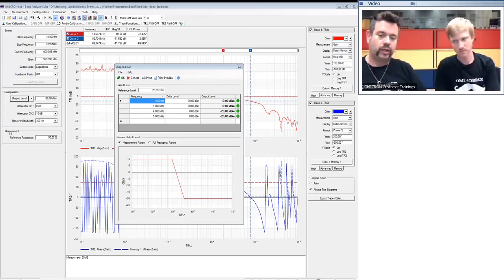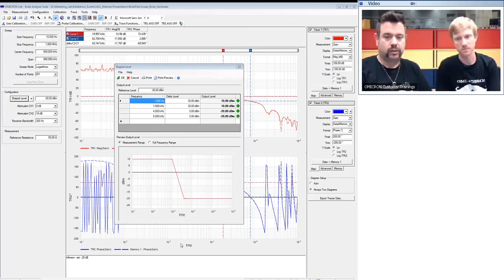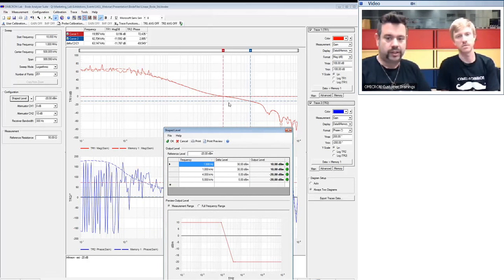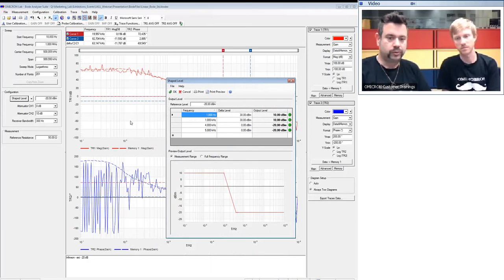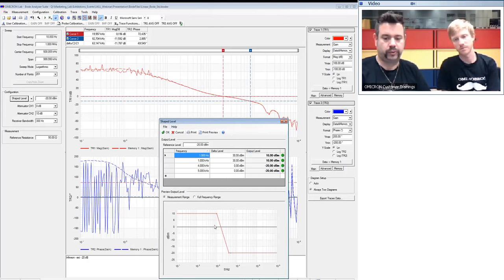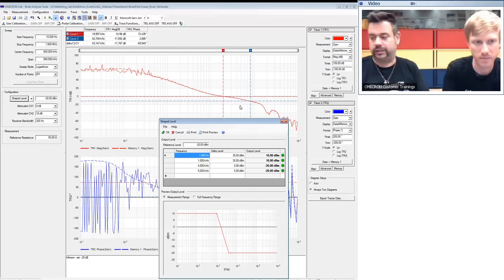Usually you have to have a small distance, so our pass-through point is somewhere in the area of 20 kilohertz, and the noise stops, as you can see here, around 100, 200, 300, 400, 500 hertz, so it's definitely enough if we just increase the signal up to 1 kilohertz and then slightly reduce it until 4 kilohertz. So we have enough security that we have the right injection level at the point we're interested in.